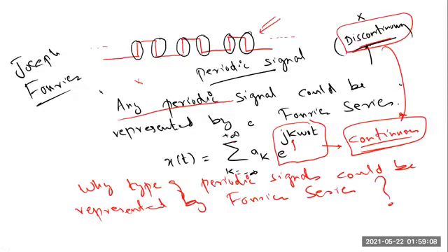The Fourier series that we have derived so far includes a linear combination of an infinite number of terms. You can see that we are going to sum from minus infinity to plus infinity. So there are an infinite number of signals, and we are adding them together, and as a result, we will be able to get exactly x of t.